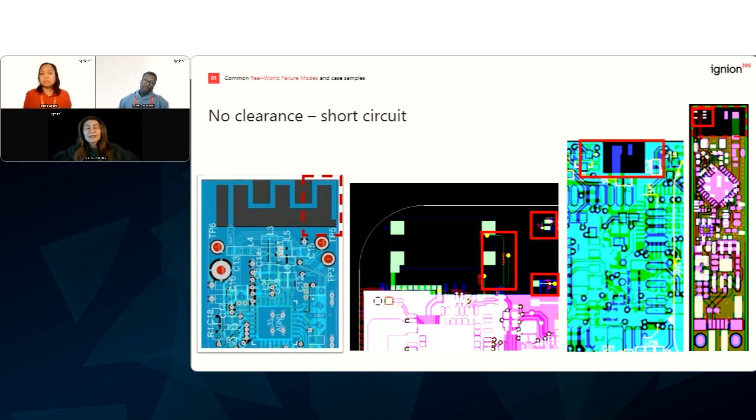Yeah, I mean, it's kind of understandable because we tend to have smaller and smaller devices nowadays, right? We don't really have place. So we can say, okay, in the data sheet, it says that it needs 5 mm clearance, but I have 3 mm. It will do. People tend to think like that because we want to have the smallest possible device, right? And we want to maybe fit more battery space there or more components or something like that, and the antenna will get less space. So I think that's why it happens.